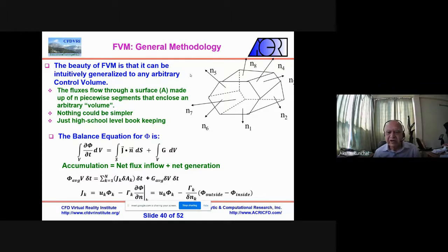So basically, each surface is treated piecewise. Each surface has fluxes going through it, and the whole control volume only has one point in it. There are no points on the boundaries, except the boundary conditions, which represent a boundary node. In other words, any volume has one node and surfaces around it, and we determine these surfaces piecewise.